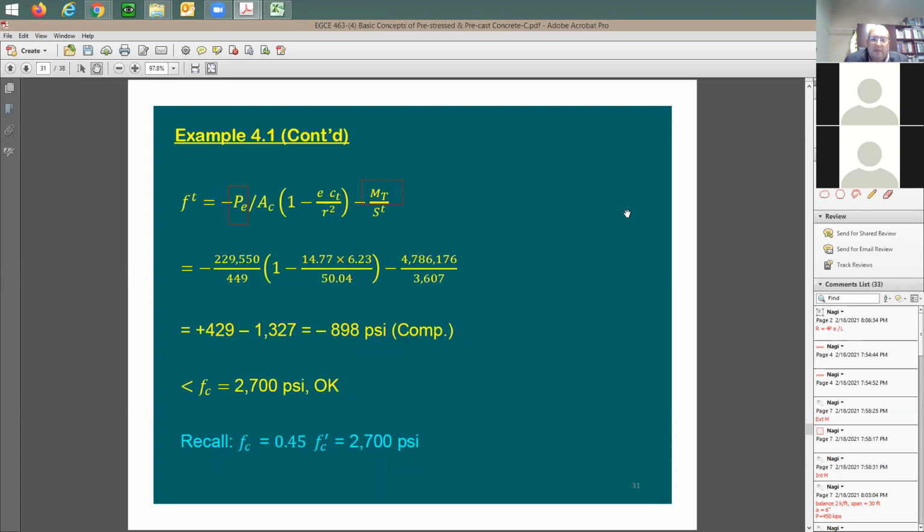That's it. I'm just changing here the condition at the effective time of pre-stress, which means after all the losses, you're going to have here the total service case. So I'm checking here two cases. One of them is going to be at the initial, the other one is going to be at the service, at the effective stress. This is all what you need to do.